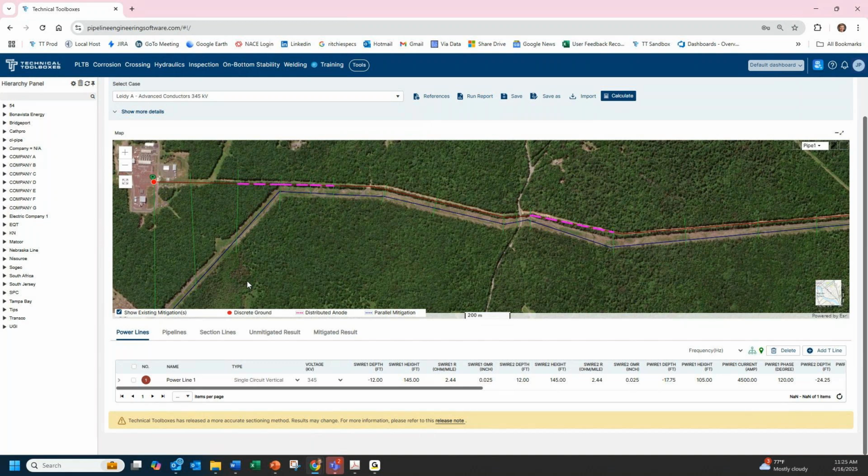And we have a simple equation to figure out, oh, that's a 345 kV line. Okay, that's a single vertical. This is how we determine this stuff. It could be a single vertical, a horizontal, or a double vertical, and you just have to fill in the blanks from that point on. Count the disks, and that'll give you an idea what's going on.